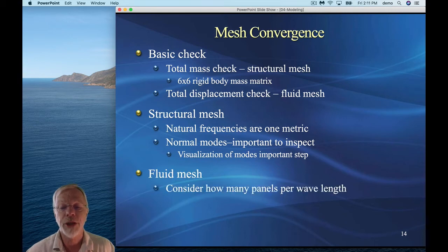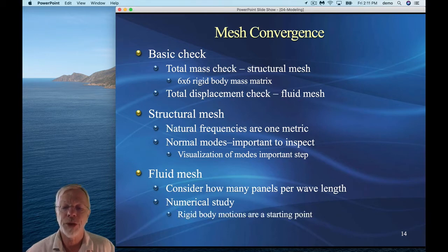For the fluid mesh, again, as we indicated before, it's important to consider how many panels we're going to use per wavelength, and a numerical study is usually required. One possible starting point is to make sure that we've converged in terms of just the simple rigid body motions.